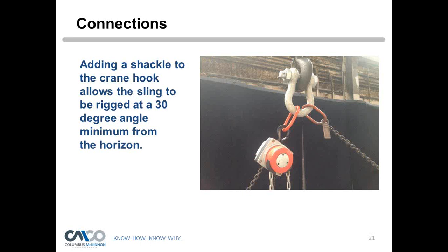It's drastically different, and it'll jump out like a sore thumb. And again, we have a webinar showing that on rigging chain inspection. But I'll send Sean that picture. Once you start learning how to inspect chain, even slight stretch will jump out at you. You'll just spot it.